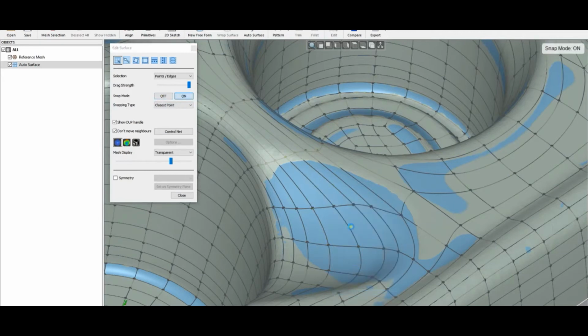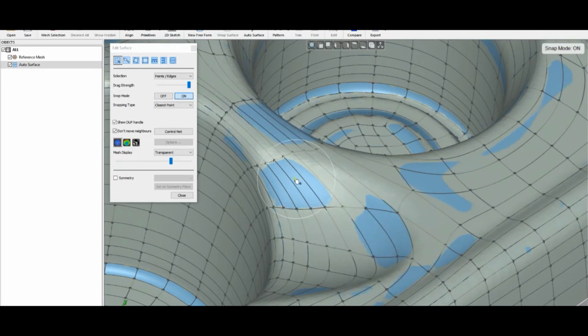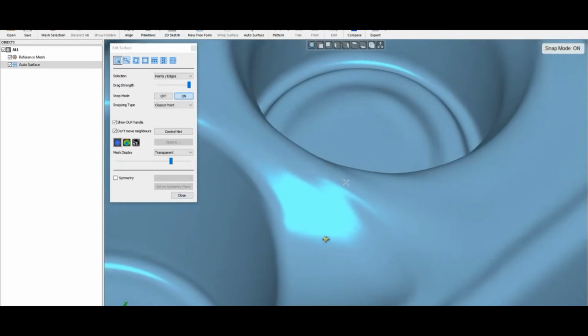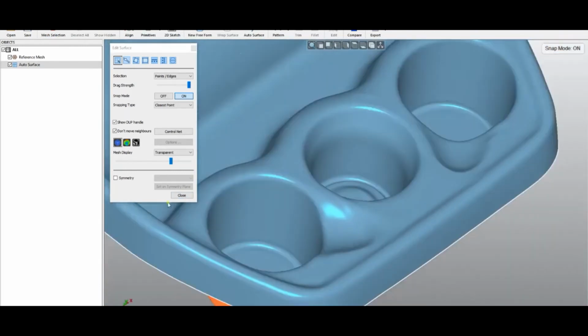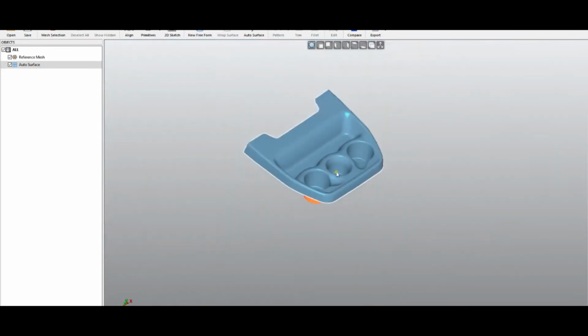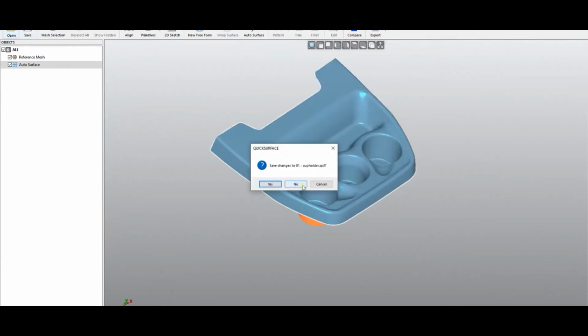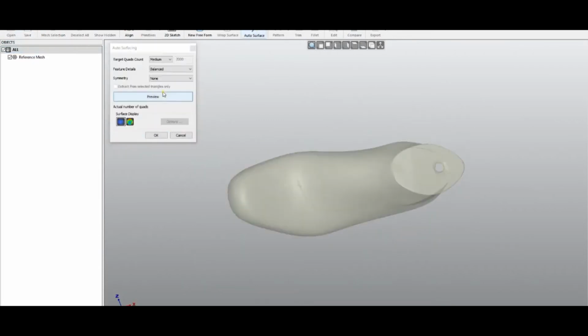Now this is off, it's not on the mesh, so I can use the function which is called snap on the mesh. In such a way I can keep my points always on my mesh, and I can see the result, and you can see that I can improve my shape. But automatic surfaces help me really a lot to get to this result which you can see on the screen. Let's move to another mechanical part like this here, and see how it will handle this. Press preview.